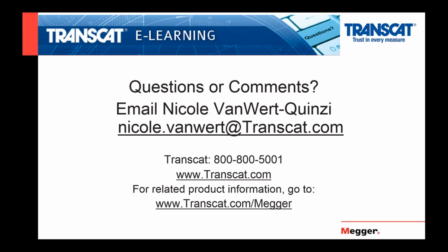If you want to calculate the ripple current, what you can also do is use the strap as a shunt. After calculating the ohmic value of a strap, you can use that as a shunt to measure the AC voltage drop across it, and then calculate the current by dividing the resistance of the strap into the voltage and coming up with the current.